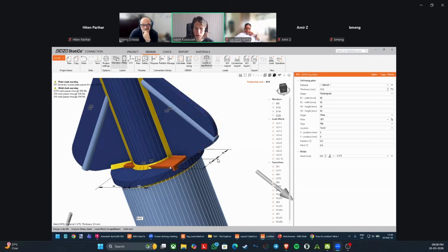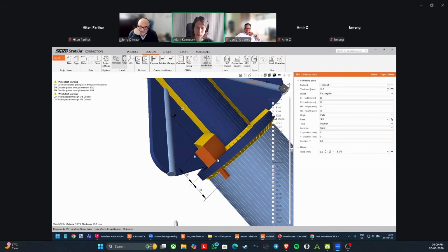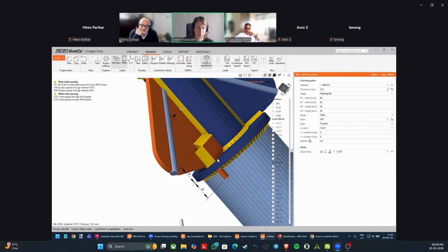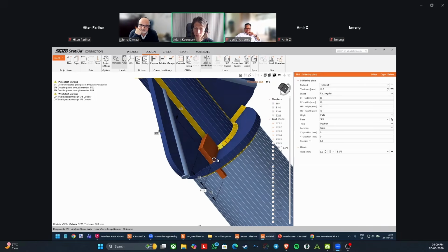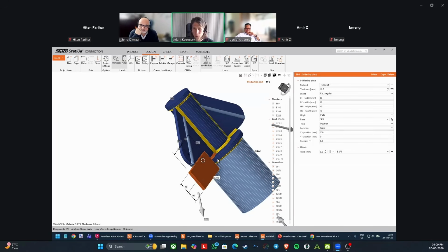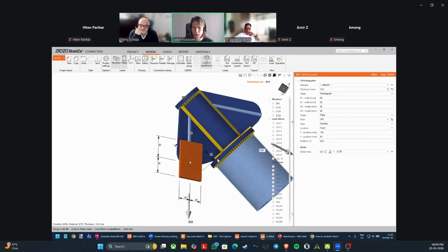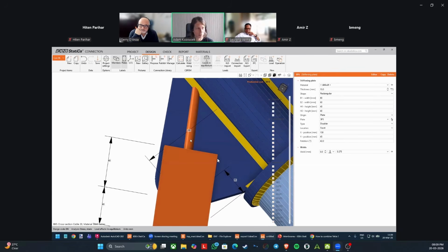Now it is a rib to this plate, and I choose not a rib, but give me a doubler. Okay. So now it looks like this, attached to the other plate. I will turn off the welds here. I don't want welds. And I will position the plate where I want it, so position in space like this and rotate it by the same rotation of the rod.